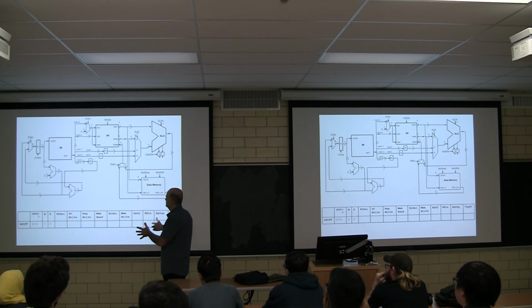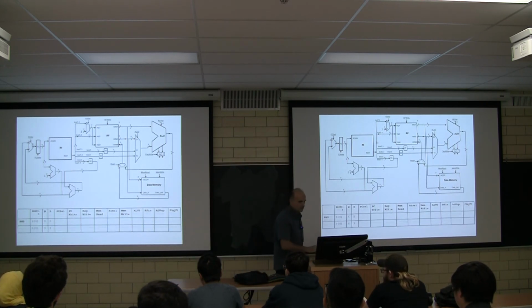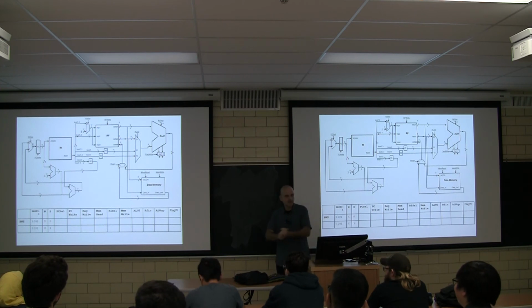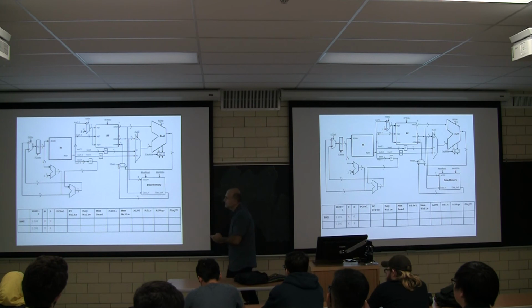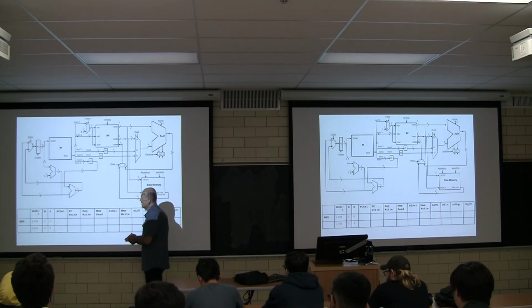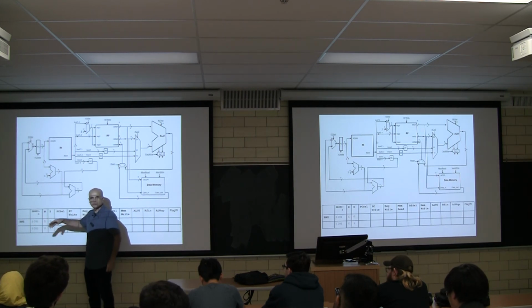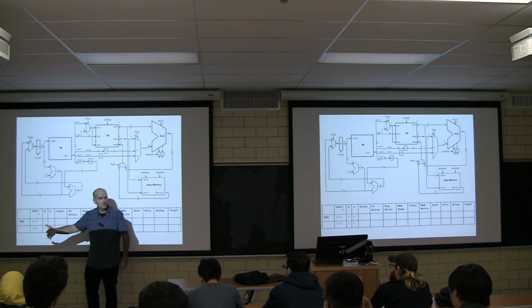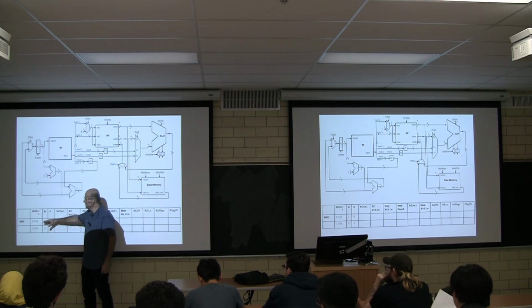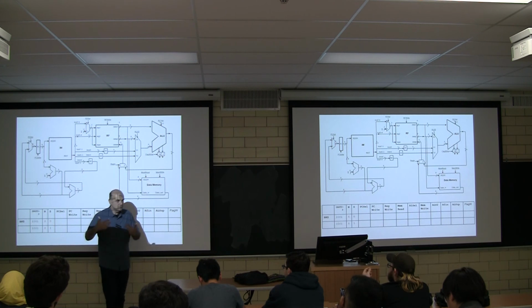Okay, good. Shift. I'm not going to do shifts. I don't like shifts. You can do that on your own. Let's do a branch, and we're done. So let's do branch not 0. Notice now that before we had both of those being X's because we couldn't care less what the condition codes were for those condition flags. Here, because this looks at the 0 flag, we expanded into the 2 rows for that.